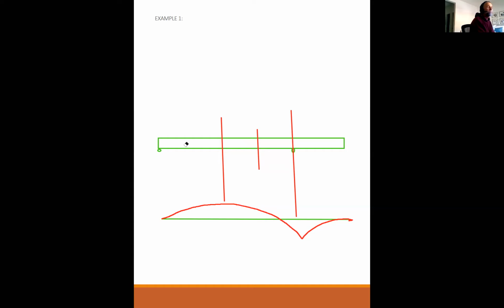So perhaps the steel I needed for positive bending, I do run it all the way out, and the steel that I need for negative bending, I run it all the way out as well. Here's the other half of the answer. You can always ignore the compression steel. As a designer, when you're designing a beam, you could ignore that compression steel, and your answer is only ever going to be more conservative than if you had acknowledged the compression steel.